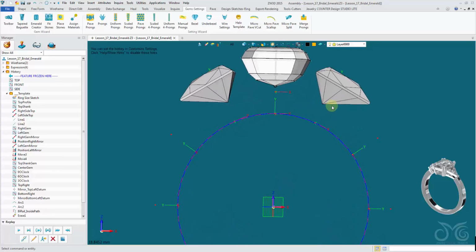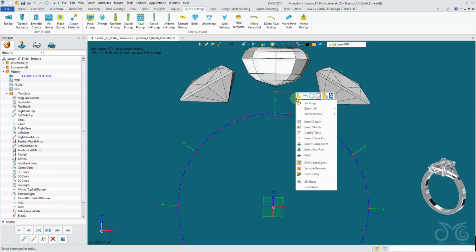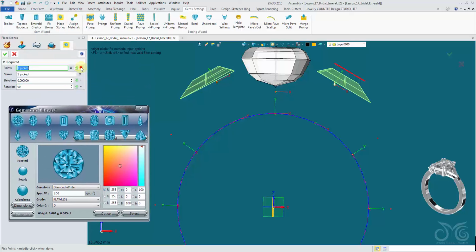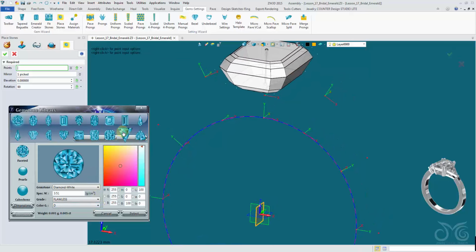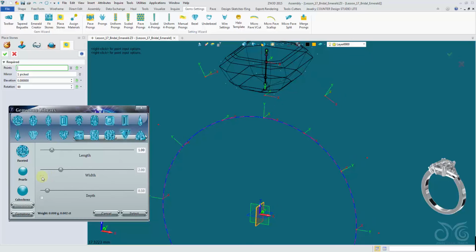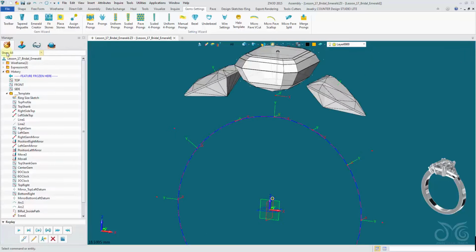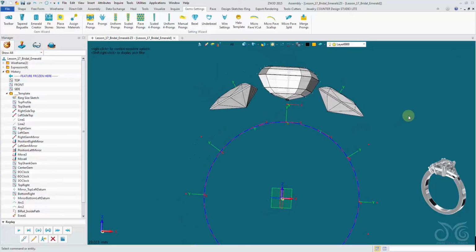Okay, I'm going to redefine that. I think I'll customize my gemstone and make it have less of a depth. Right click, redefine last. Okay, to do this I need to unpick my triangle cut stone and then replace it with the different dimensions. So I'll activate the depth and the width. Length 5.5, width 5.5 as well, and the depth, let's say 2.5 millimeters. Okay, so I just reduced the depth of the stone there.